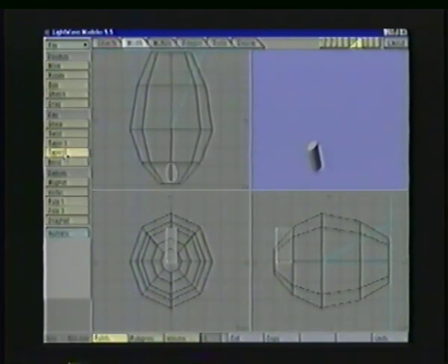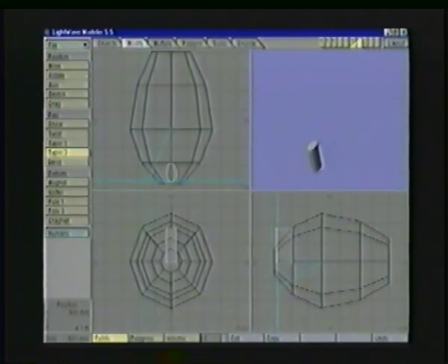Here I could go ahead and use the Taper 2 tool. You may notice that if you've been dragging out with the right mouse, your area of influence, or your range, is defined. How do you get rid of that? It's simple. It's just like deselecting polygons or points. I deselect that tool by clicking in the gray area, or I could do that in the numeric panel as well. Now I'm going to need to place my cursor in the face view.